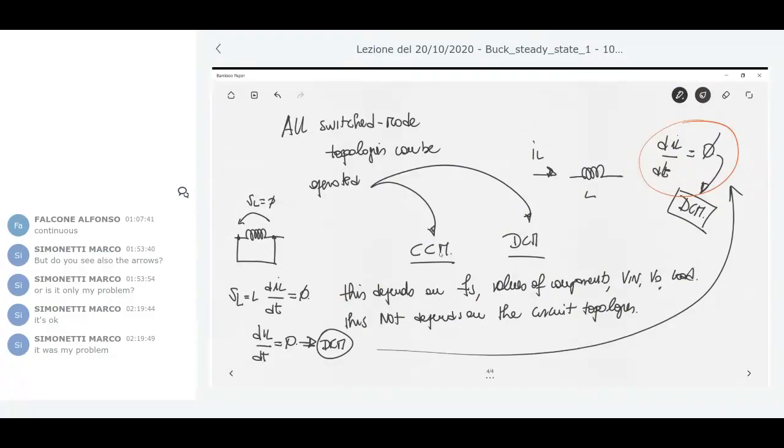The current can be, let's say, constant at a certain level, but the derivative is null. So as you can see, the correct definition is made by looking at the time derivative, but for the totality of the cases, it's enough that you look at the time behavior of the current flowing to the inductor. Look at the current, and then you can say something about the operating mode. So this is just a very short introduction about what we'll see in the next weeks.